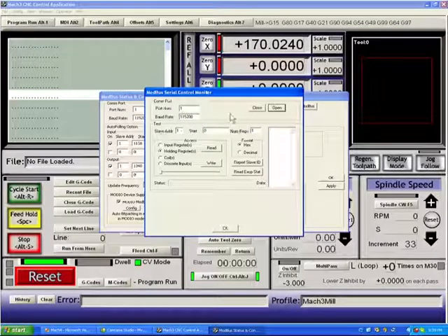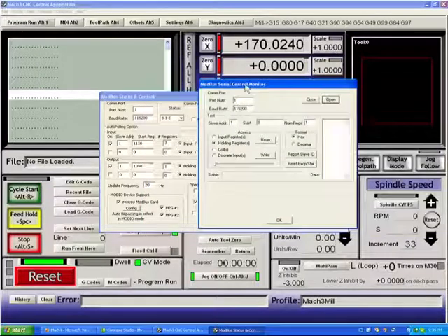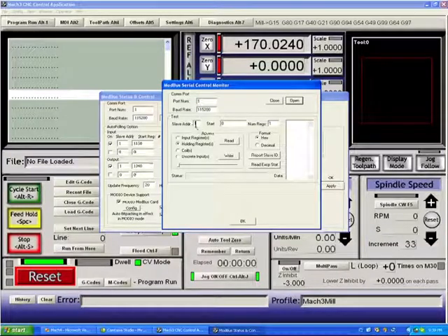But in reality, there's a limit of 2 due to issues of getting it too complex. If you had 4 running, you're going to be limiting yourself. I'll go into that in a moment, though. So here we have the slave address of Peter's board that I have hooked up, and it's slave number 1. Here we have a start parameter, and this is a start address. Now, Peter's board, starting at address 1150, has about 7 registers